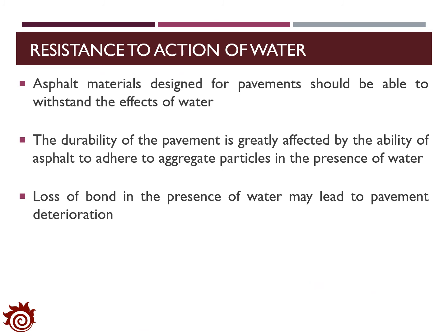We know that water content has a significant impact on the performance of the pavement. In that sense, the asphalt materials designed for the pavement should be able to withstand the effect of water. Usually, the durability of the pavement is greatly affected by the ability of the asphalt to adhere to the aggregate particles in the presence of water. The loss of the bond in the presence of water may lead to pavement deterioration, and this will significantly reduce the performance of the pavement.